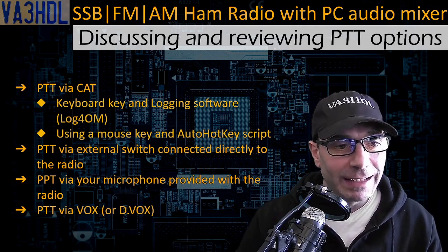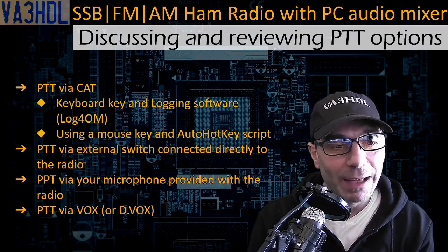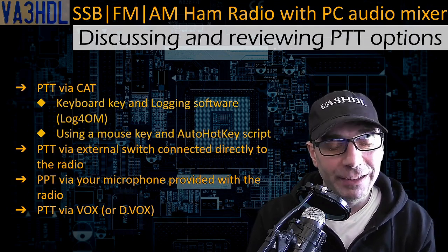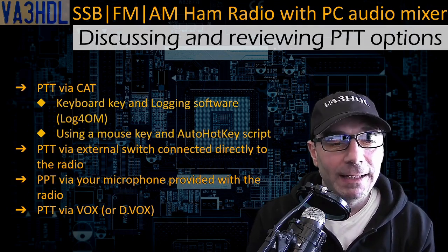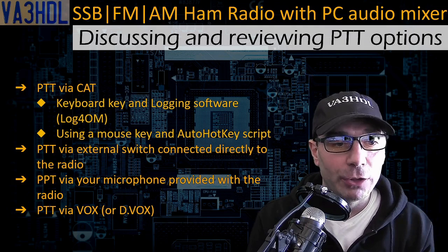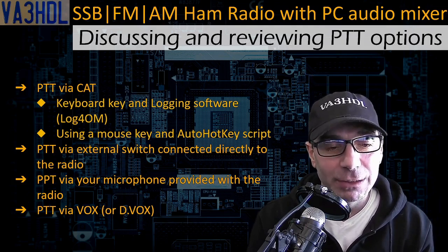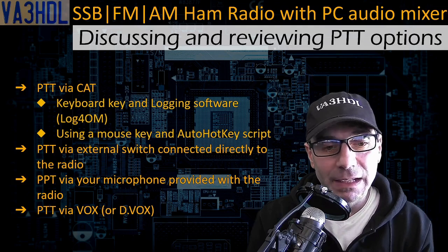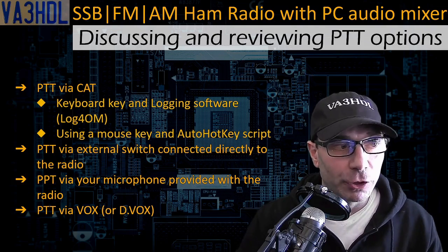And the last option is PTT via the VOX command or digital VOX when you turn that on in your radio. And I am saying digital VOX because in the case of the ICOM 7300 or the Yaesu with the built-in USB audio, you need to switch VOX to digital VOX to work for this purpose.